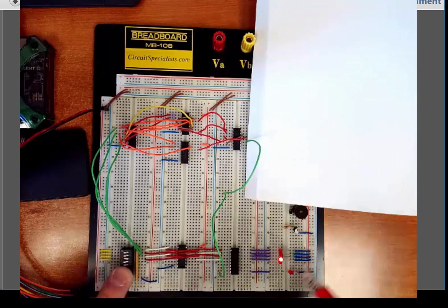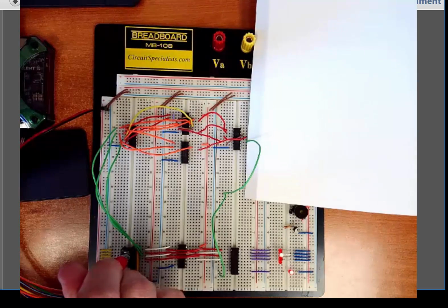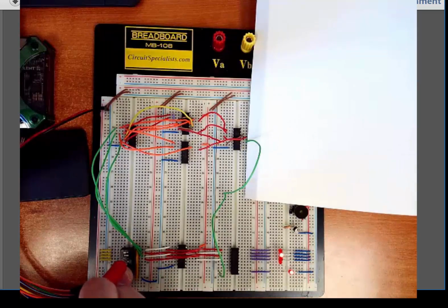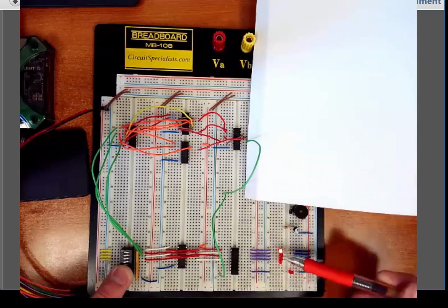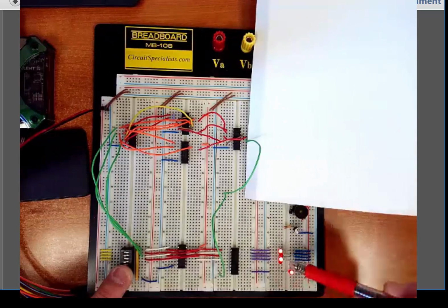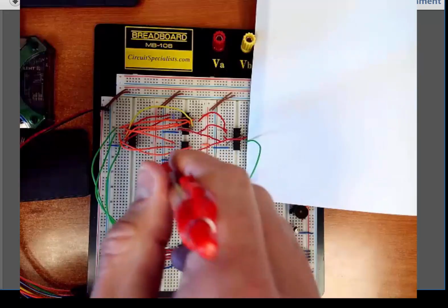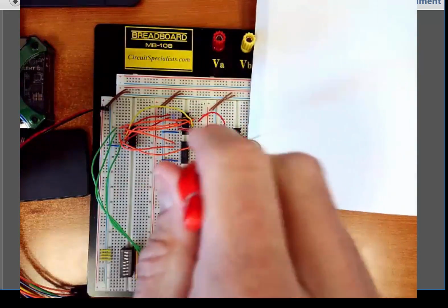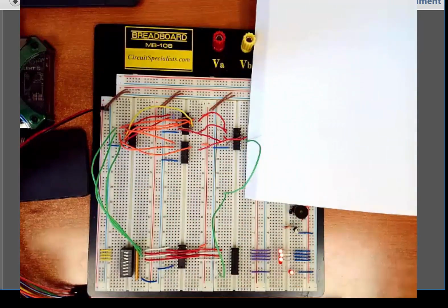And it's going to operate exactly the same as a canonical form, but with fewer gates. So as I go through them, I've got A, B, and C here. It's 0, 0, 1, 0, 1, 0, and notice that the output is asserted. So I have it asserted for decimal 2, it's asserted for decimal 3, then we go to code 100, which is 4, it's not asserted. 101 is 5, it is asserted. 110, it is not asserted, and 111, it is asserted. So this is a minimized sum of products logic expression that's implemented on your breadboard, and you drive through it just like that.